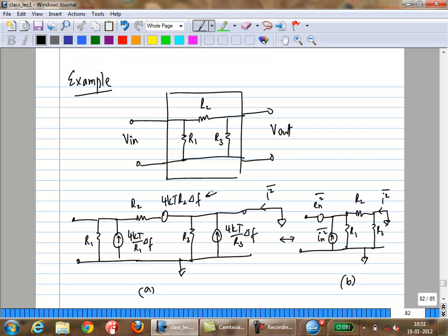You will have to keep track of the signs. If they are correlated, the real noise is actually lower. Well, it depends on whether it's positive correlation or negative correlation. In the case of a simple resistor, it's probably going to be lower than the direct sum of the two.